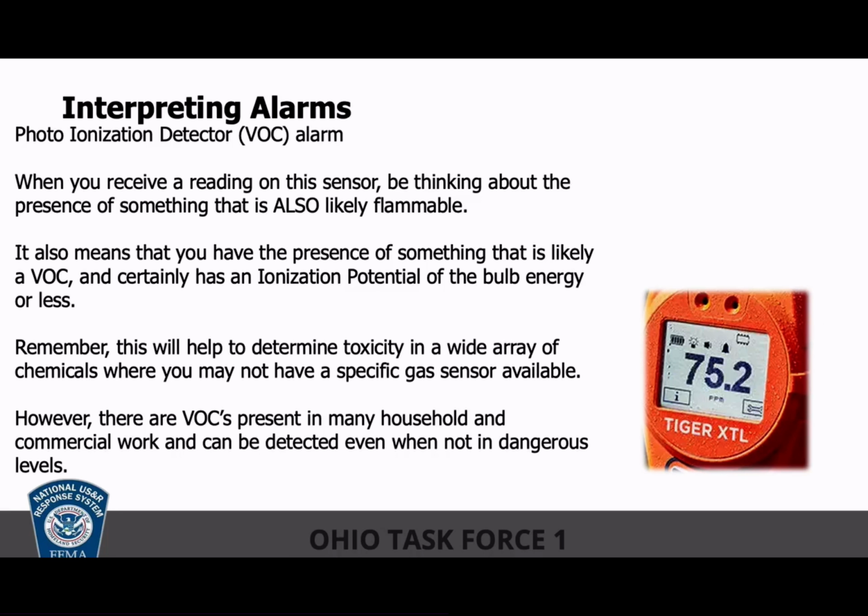As far as VOCs go in our PID detector, just remember that the PID is not always picking up VOCs. There are lots of inorganic or volatile inorganic compounds that it will also detect, but probably 90% of things are going to be volatile, carbon-based compounds. If you're getting a hit on the VOC, you should also be thinking about it being flammable.